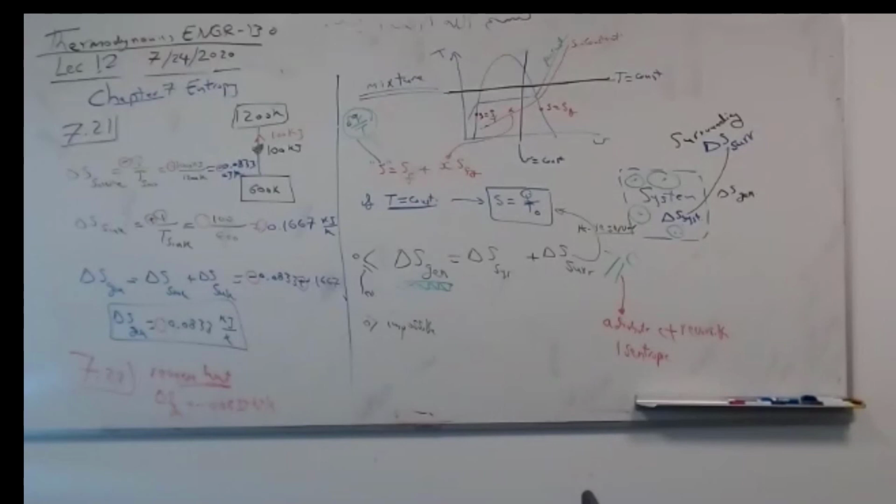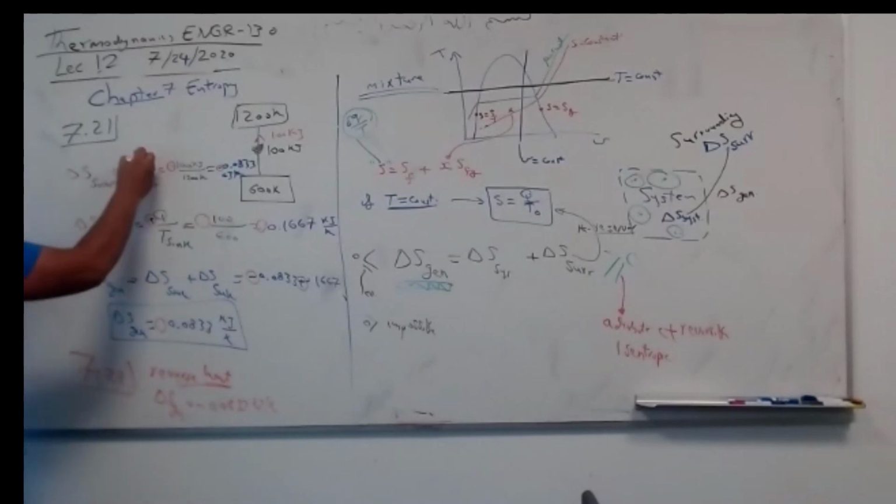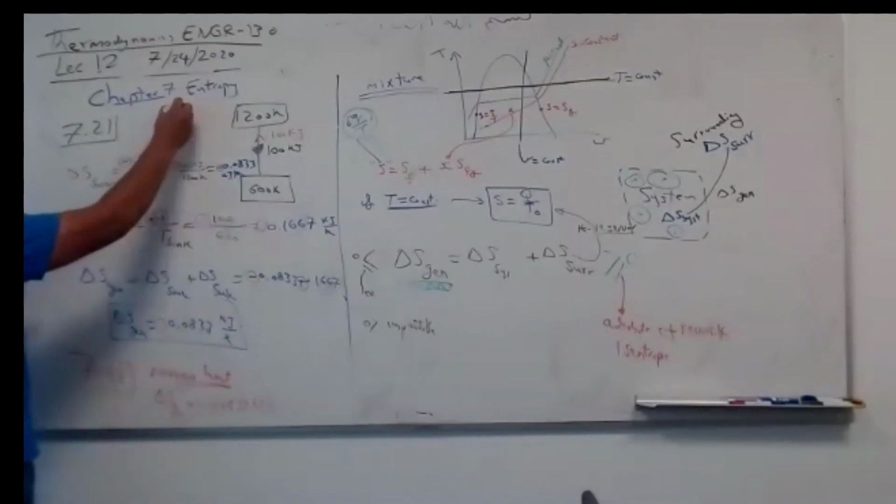You will always hear me say heat per unit mass. Why? Because there is no specific heat. Heat is not a property. Specific applies to properties: specific enthalpy, specific entropy, specific internal energy, specific volume. But you will never ever hear me say specific heat. So we need to be dedicated to definitions. Heat is positive. It's addition.